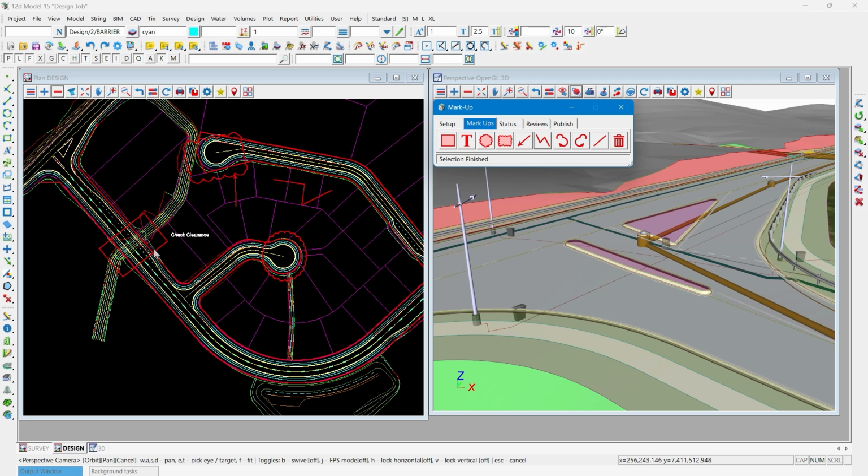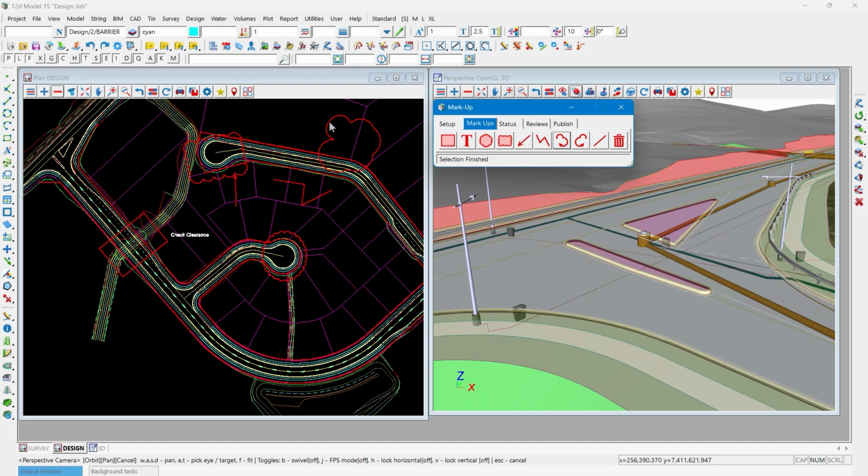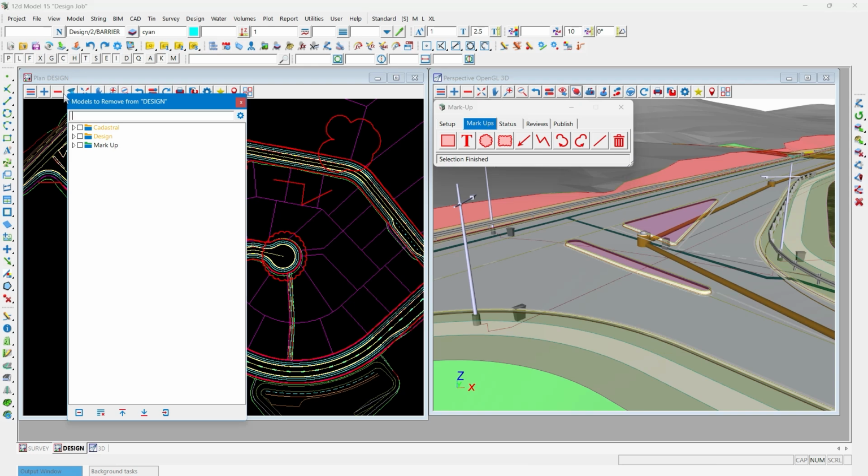We have anti-clockwise and clockwise clouds. This allows you, if I do a clockwise cloud, to essentially draw my own odd or irregular shaped cloud. And again, to complete that cloud and to close it off, if I just hit escape on the keyboard, that's going to close that cloud up for me. So for the purposes of this demonstration, I need at least 4 items so I can take you through the status gateways. All of these models and all of the attributes are being automatically added in the background, so it's giving me unique model names for each of those markup items that I'm producing.